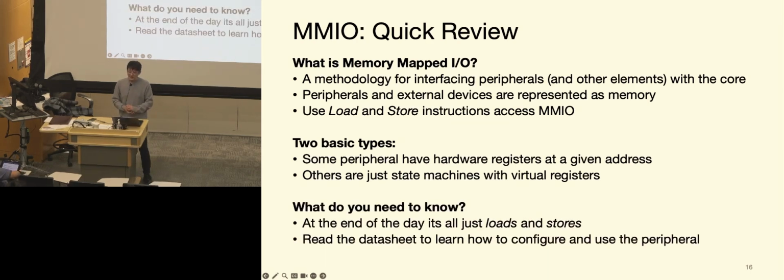And at the end of the day, this is what's important. These are all just loads and stores, and then you will be able to read the data sheet and learn how to configure and use each of these peripherals. But at the end of the day, they're basically part of the memory. You can think of them as part of memory, and you interact with them just the same as the rest of the SRAM or flash.